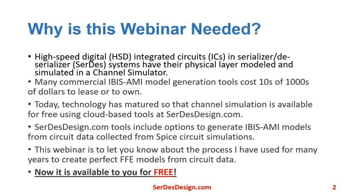Why is this webinar needed? High-speed digital integrated circuits and serializer/deserializer systems have their physical layer modeled and simulated in a channel simulator. Channel simulators are designed to use IBIS-AMI models that are based on the IBIS specification. Many commercial IBIS-AMI model generation tools cost tens of thousands of dollars to lease or to own.